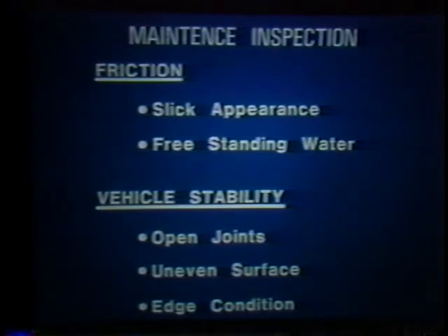Then, the areas should be visually identified so that improvements can be scheduled. Often, what seems like a minor repair is in truth an indication of more severe problems. Sections of pavement containing edge raveling, roadside wheel ruts, and separated pavement joints should be identified and programmed into future maintenance projects. If they are left unattended, the repair costs will be much higher.